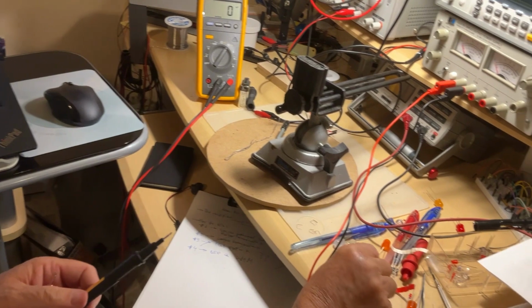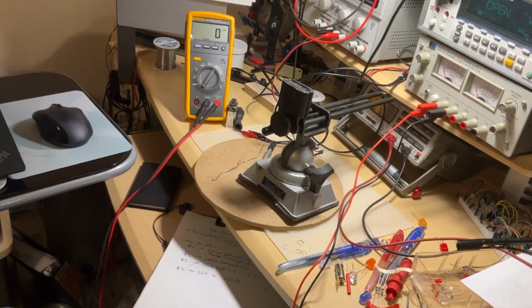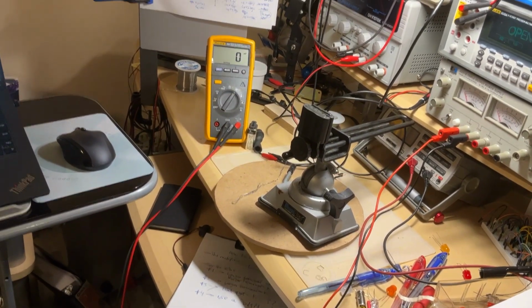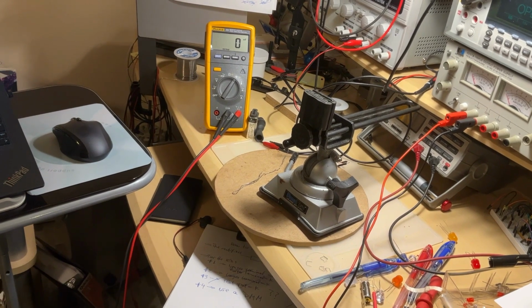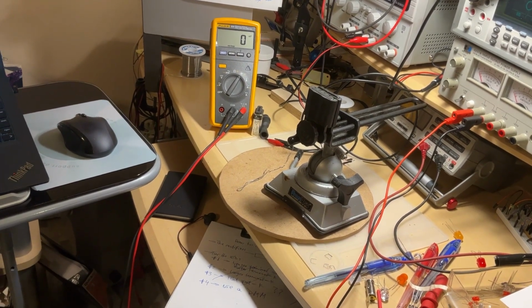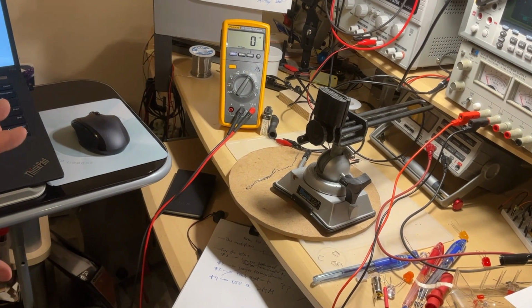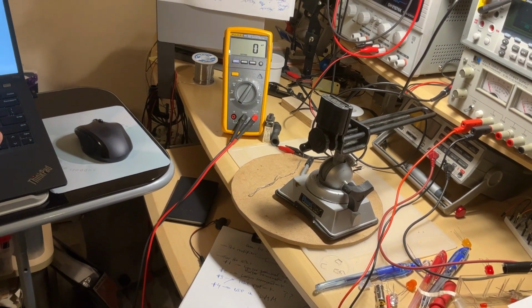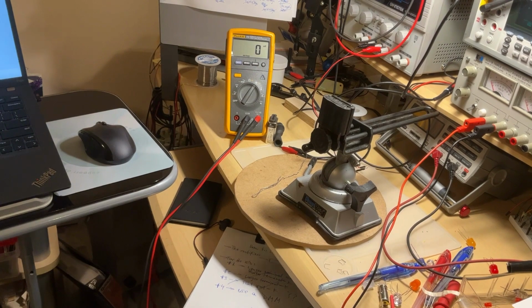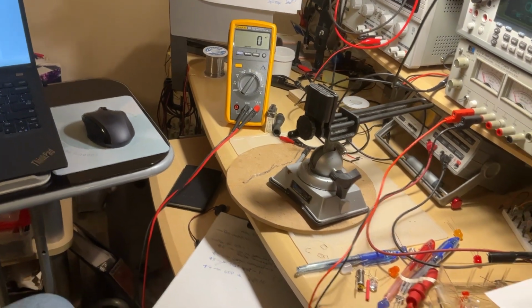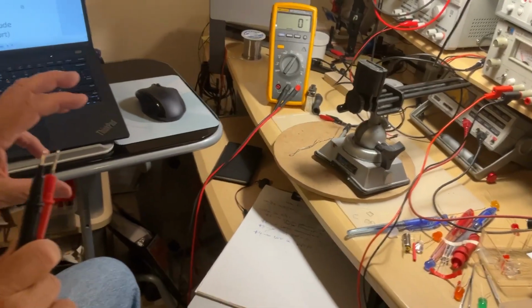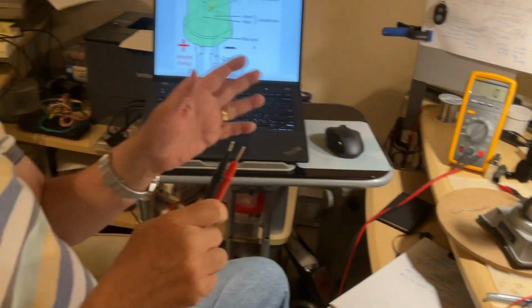So guess what? Older meters are better, because for the new meters, the reason why you can't see the light on some diodes is because all the meters, the new ones especially, were designed with power saving in mind. So the current inside the diode is so low that the diode won't be able to emit the light.